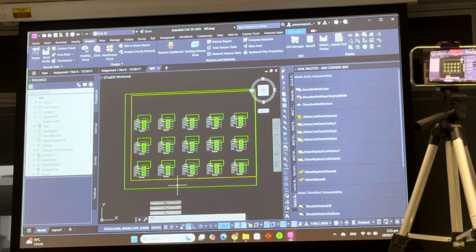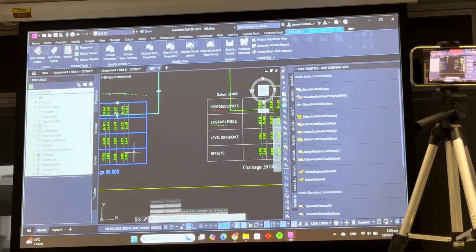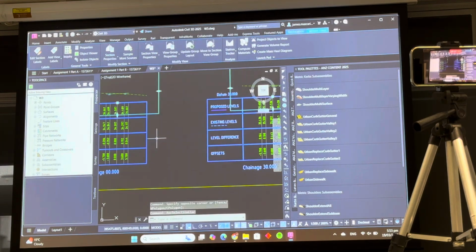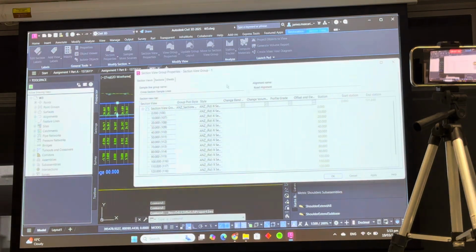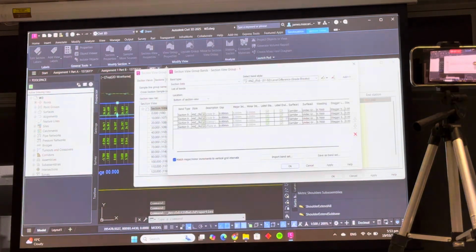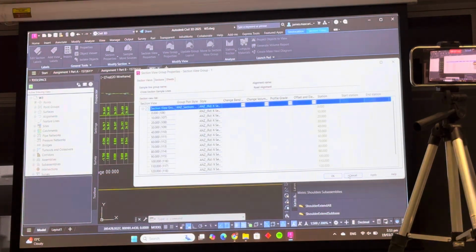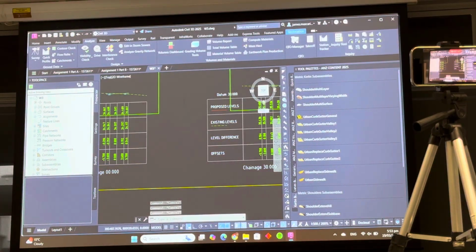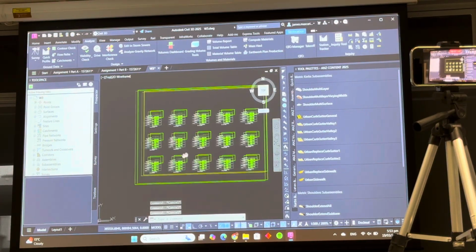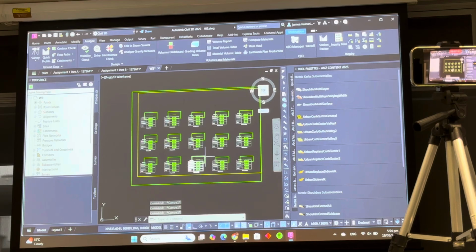Can you do it again, Jim? Sorry. So you click on one of them, select similar. You go view group properties, and you just change band, and then your views. Your bands will be named differently. You can still do it the way I demonstrated, but this obviously will save you some time. So you can go back to old school, or you can do it this way, if you didn't realise that was how one could do it.